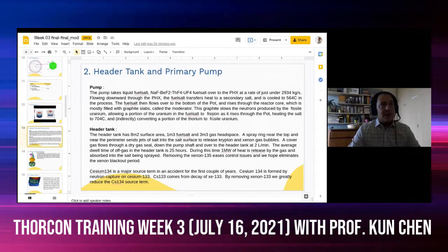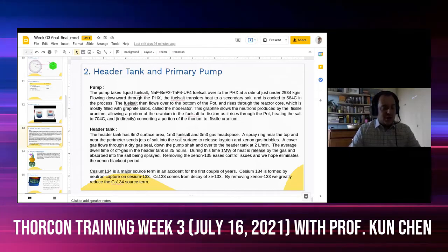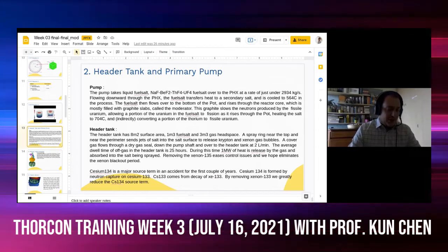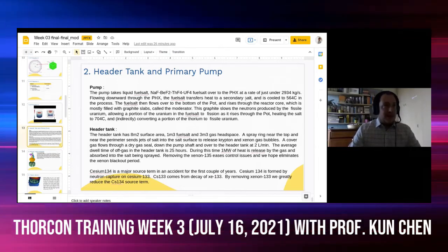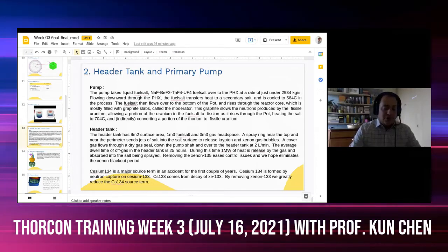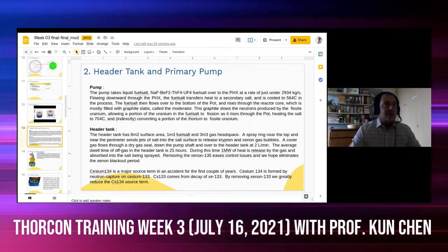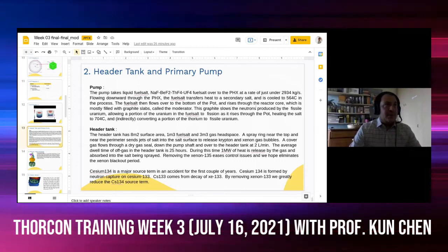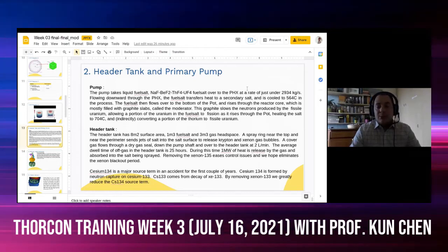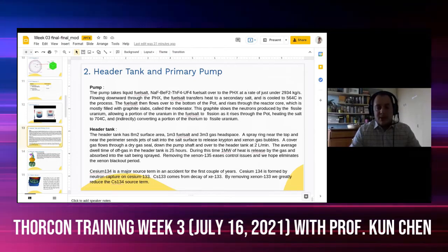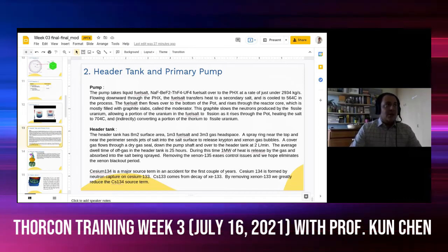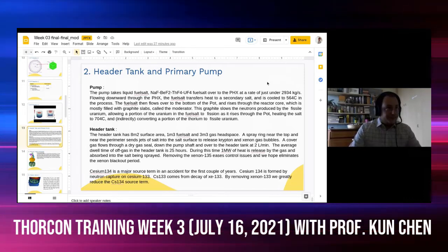The circulation time, again, has changed in recent designs due to a more accurate estimation of the salt capacity, but let's say it is in the order of 10 to 15 seconds recirculation time. That means that we have to move around more or less 1 cubic meter of salt per second. So that dictates the requirement of the pump.